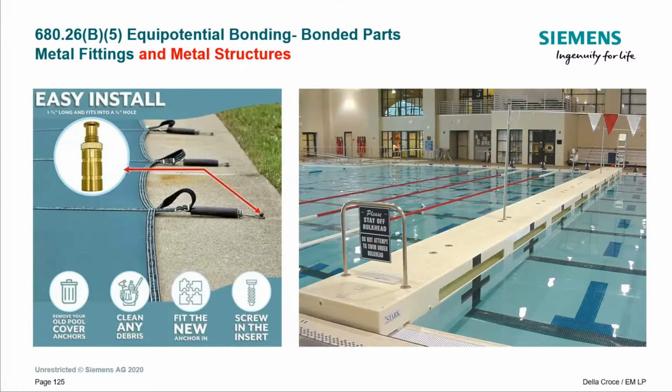As we're talking, I'm looking for a picture, to see if they actually make a metal one. And guess what? They do. I'm finding pictures of stainless steel bulkheads. I'm saying this exception only addresses a non-conductive one, one made of non-conductive material. So I don't think we have to go down this rabbit hole, but does a conductive bulkhead require equipotential bonding? It's metal within 5 foot. And there might already be a track system that takes care of that.